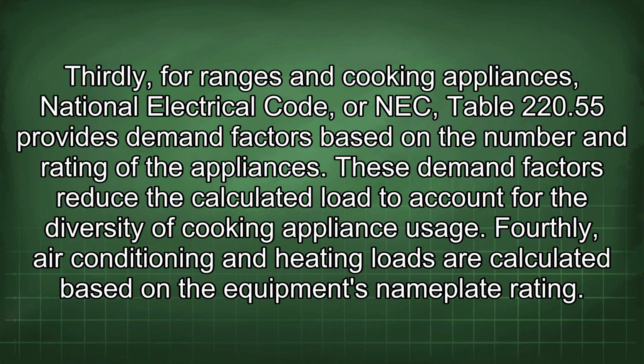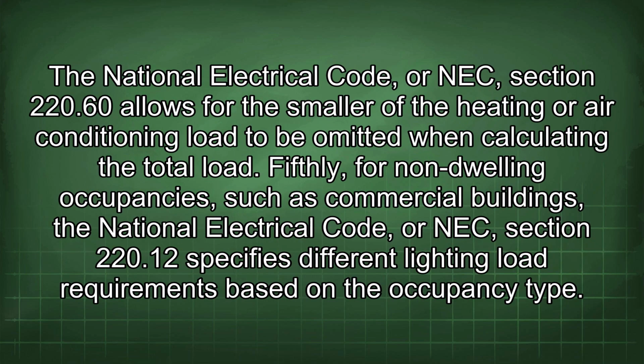Fourthly, air conditioning and heating loads are calculated based on the equipment's nameplate rating. The National Electrical Code, or NEC, Section 220.60 allows for the smaller of the heating or air conditioning load to be omitted when calculating the total load.